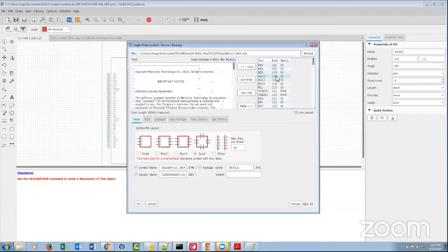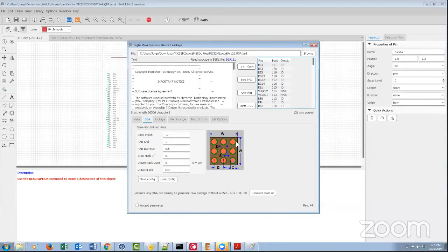It's like a grid type of configuration. A1, A2, A3, and then B1, B2, B3, and so forth. Correct. So because they didn't do it that way here, if you try to make a BGA off of this one, as it is right now, you're just going to get a big long straight horizontal line because it doesn't follow the naming convention that's expected for a BGA.